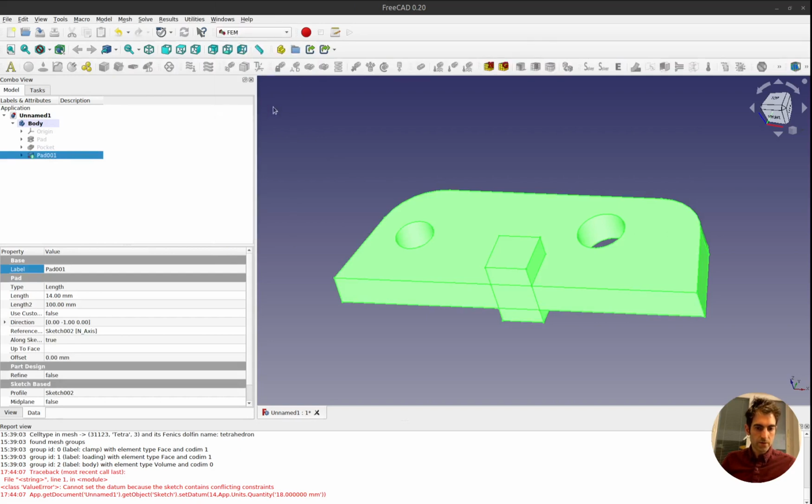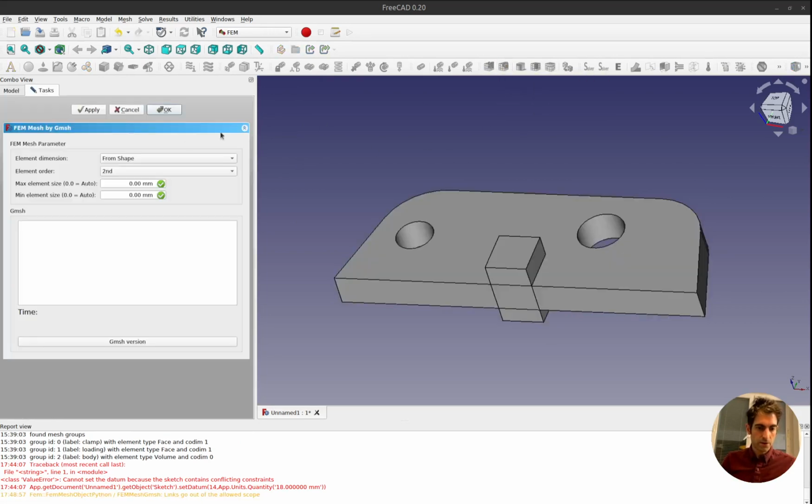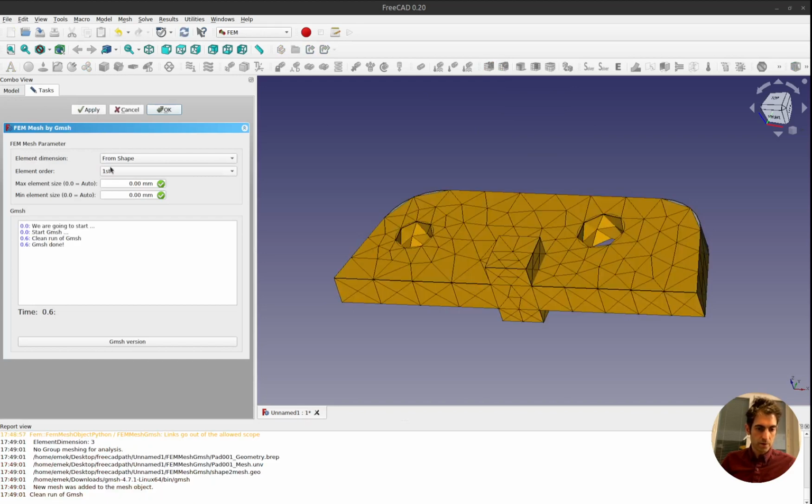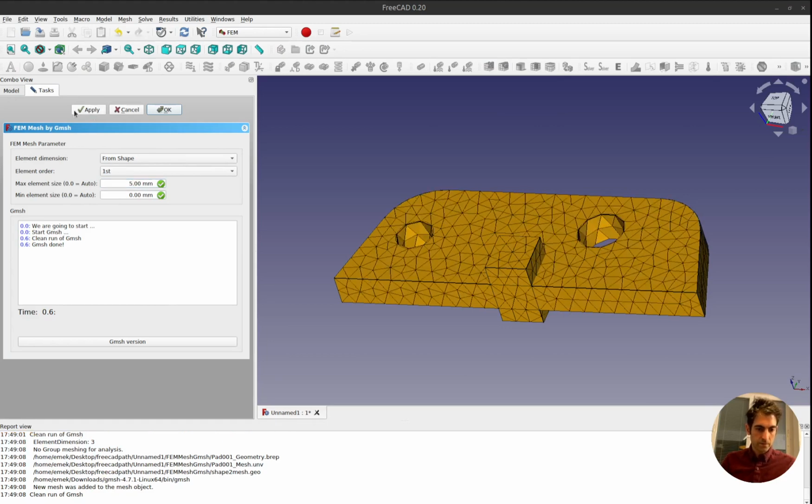Let's go to FEM, and again for the direct problem in FEniCS, what we need to do is the mesh, only the mesh. We don't need anything more, so I'm not doing any analysis. Instead of that, I'm just clicking on the Gmsh, and now I'm giving it simply a coarse one. Of course, I can try to make it a little bit finer. So maybe this is finer, yeah, just a bit. I can try to make it maybe 2.